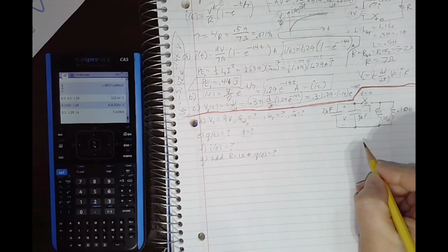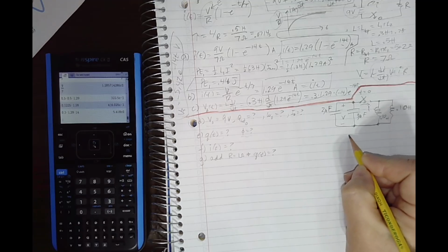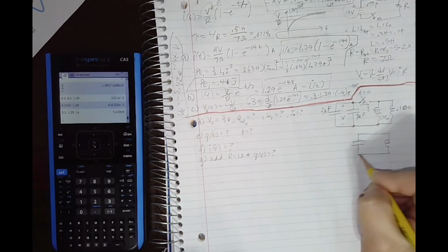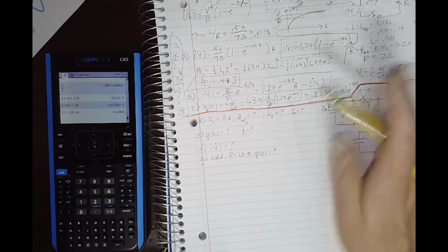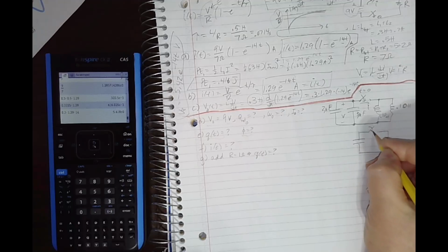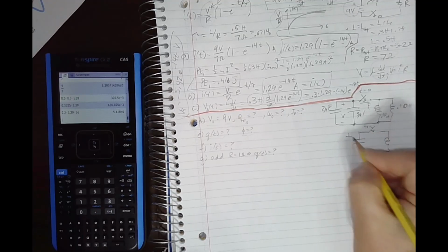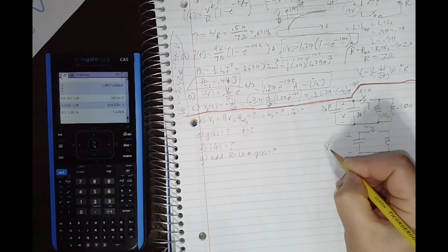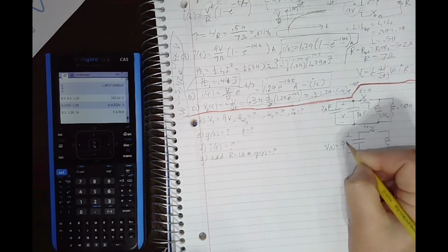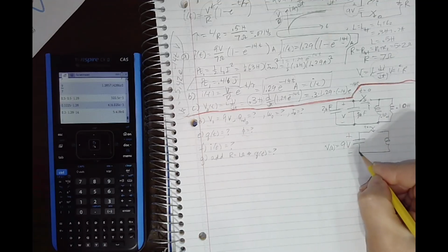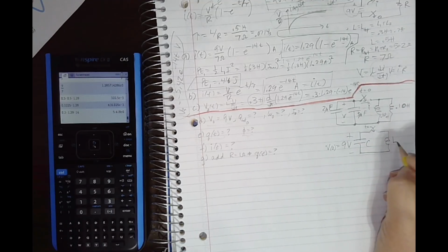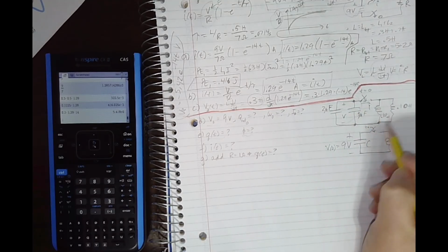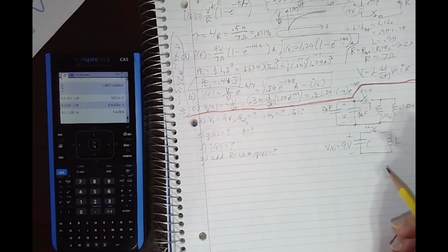Okay, but back to our circuit, we have just a nice ideal LC circuit. But let's go ahead and make it even more ideal, where there's only 2 elements, one L and one C, and that's because that's what the equations are for. And again, we'll have this t equals 0, and V of 0 is 9 volts on the capacitor. Okay, so what are these capacitance values and inductance values? How's everything connected? They're all in parallel. Hopefully you can see that.